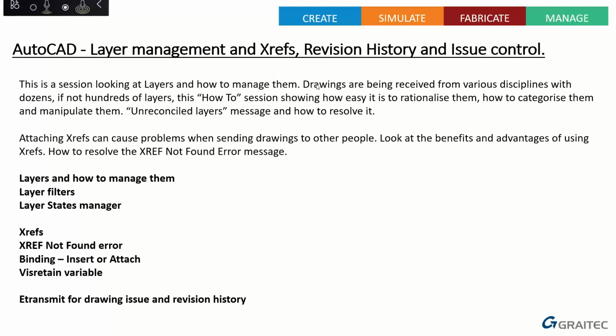So layers, you'll be getting drawing files in from various disciplines, dozens, if not hundreds of layers. I want to show you how to manage those layers, rationalize them, categorize them, and so on. And I'm sure you've seen that message popping up, unreconciled layers. And it's just a pain, isn't it? You keep closing it, and every time it pops up again. I'll show you how to stop that happening.